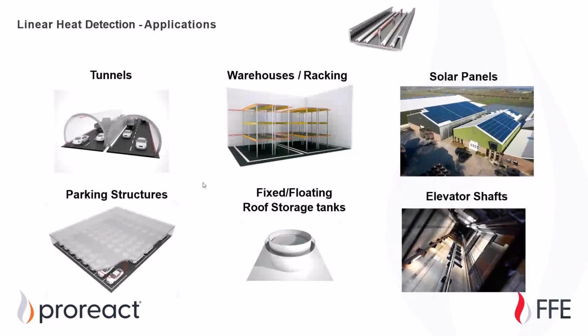So the top applications for linear heat detectors: you have road tunnels. This is in the NFPA standard, 502, I believe it is. And a lot of those environmental factors that we talked about, your dust, moisture, airflows, constant use, limited access, apply to road tunnels, as well as subway or underground train tunnels.